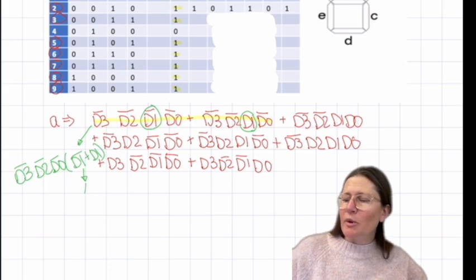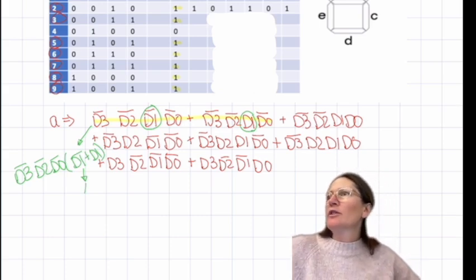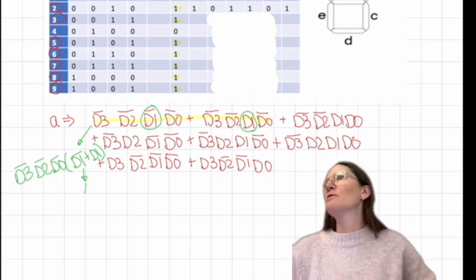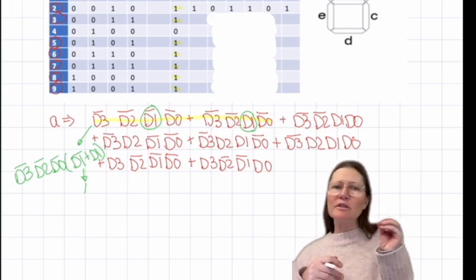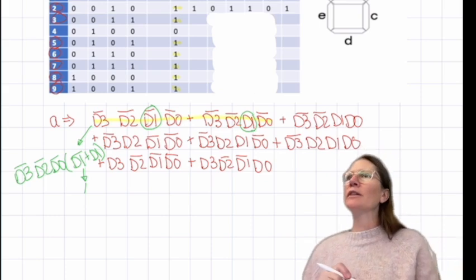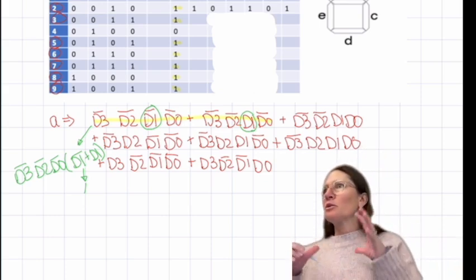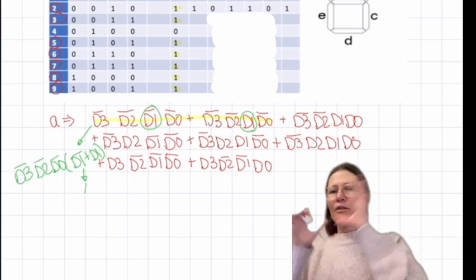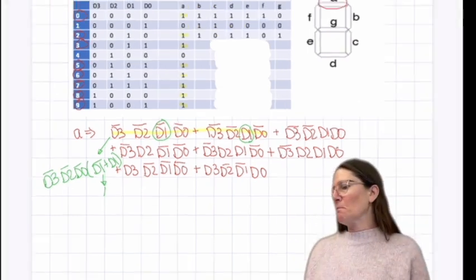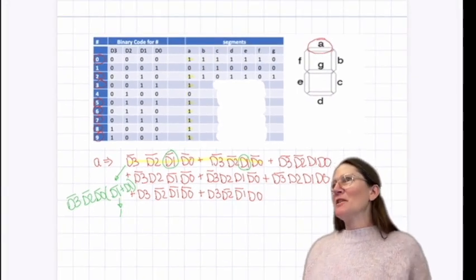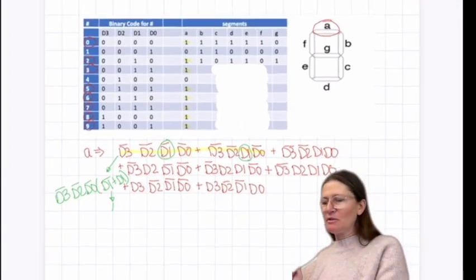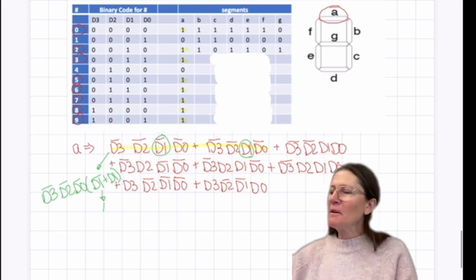And remember, this one is always a 1. So you could reduce this to a 3 input from a 4 input. So you can slightly reduce this logic down to have fewer gates, or you can implement them with all of those gates for the one segment. I thought it might be fun to go through that, but we just don't have quite time for that.